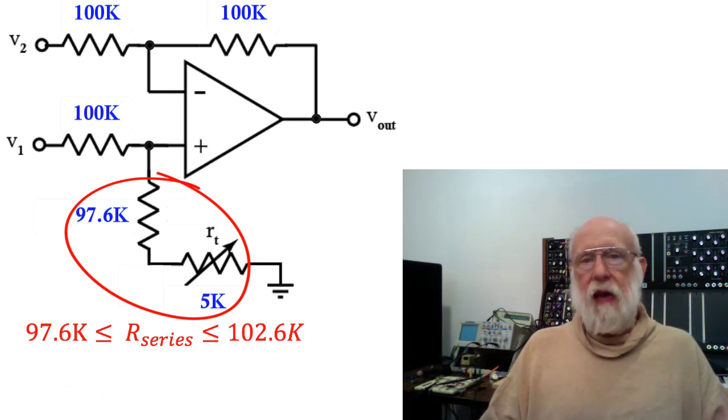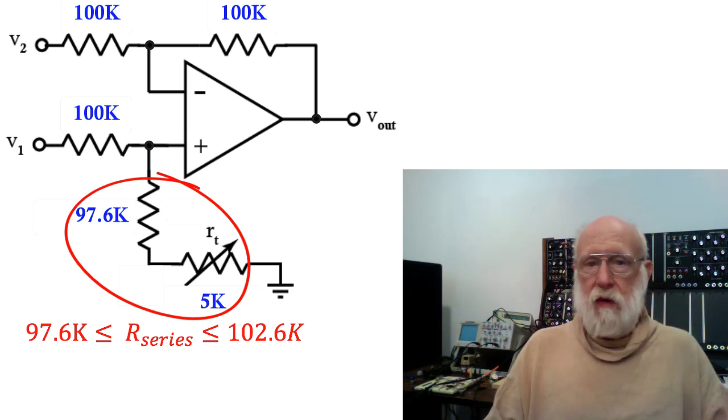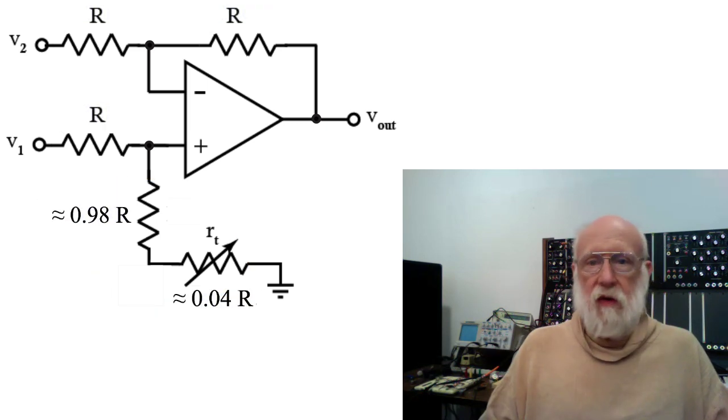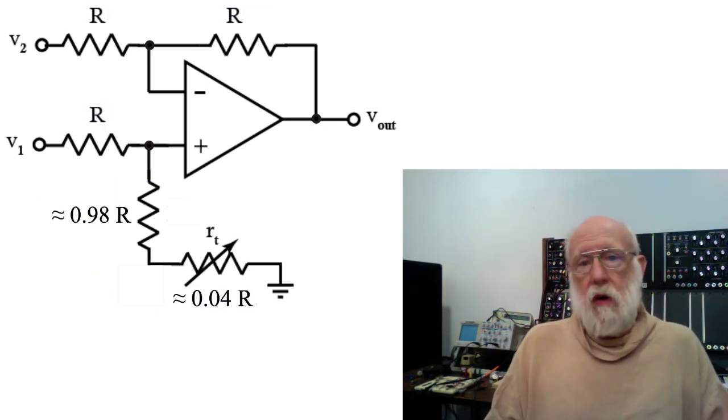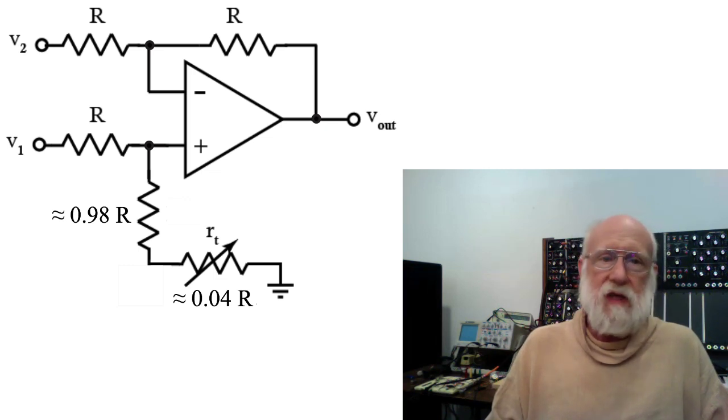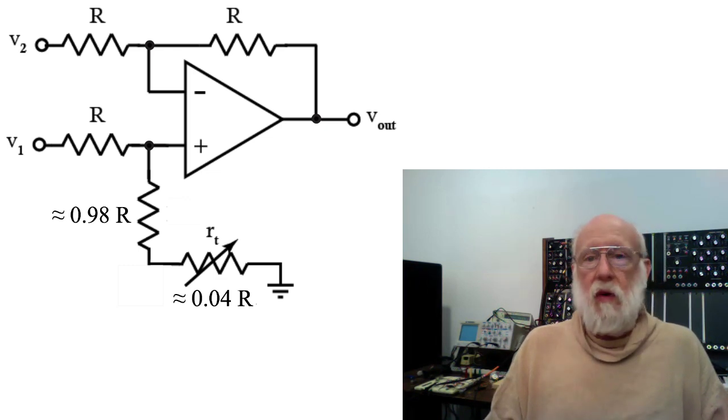And that should allow you to very precisely balance that circuit and get rid of that common mode signal. There are some other issues with common mode signals having to do with what are called ground loops, which have to do with the fact that ground paths aren't perfect. They actually have some resistance, and we will talk about that in another video very soon.